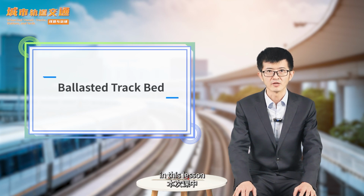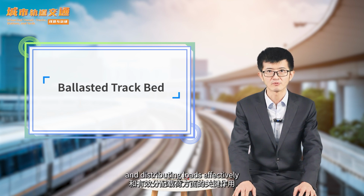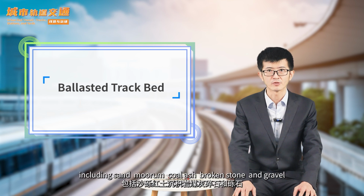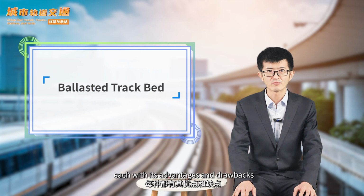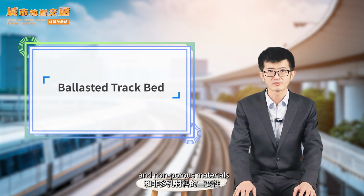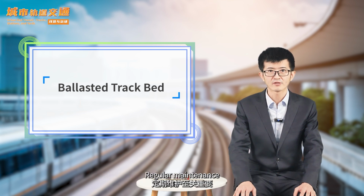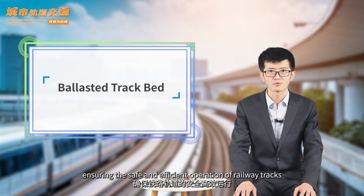Okay, in this lesson, we explored the critical role of track beds in supporting railway tracks and distributing loads effectively. We discussed the various types of ballast materials, including sand, mortar, coal ash, broken stone, and gravel, each with its advantages and drawbacks. We highlighted the importance of selecting durable, hard, and non-porous materials that offer efficient drainage and cost-effectiveness. Regular maintenance is crucial to address ballast deterioration and maintain track alignment, ensuring the safe and efficient operation of railway tracks.